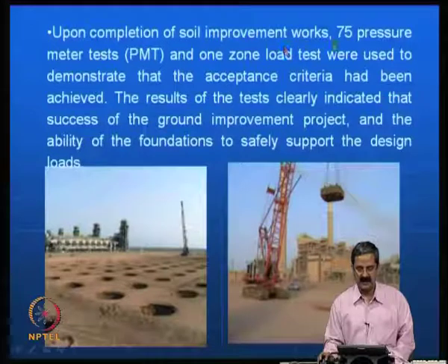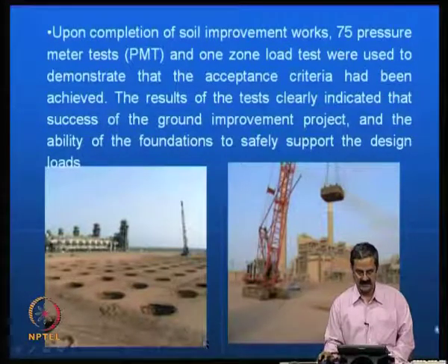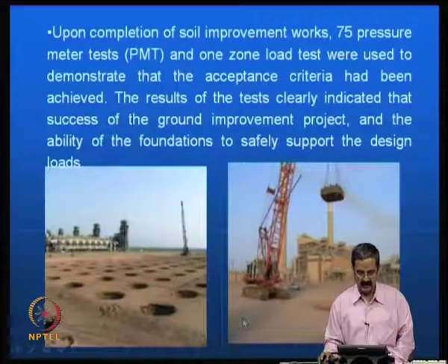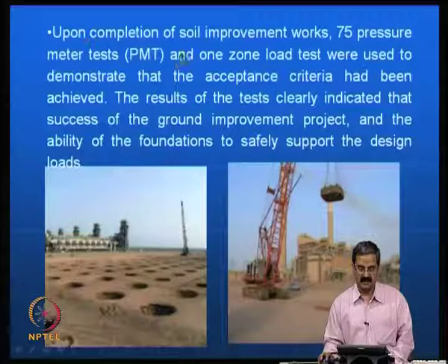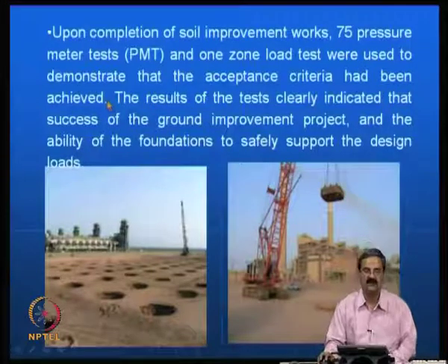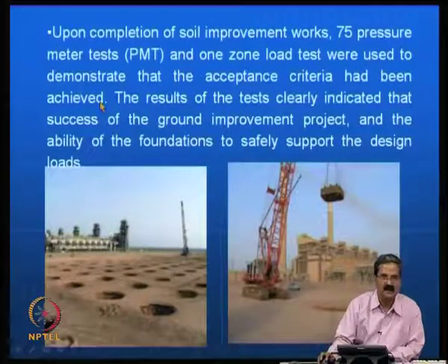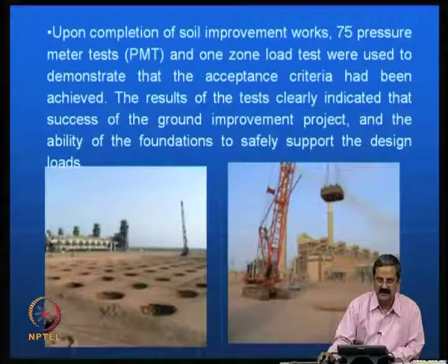Upon completion of the soil improvement work, this is the type of work that they have undertaken. This is from the particular company. They did 75 pressure meter tests and load tests to demonstrate that the acceptance criteria had been achieved. The acceptance criteria are what? The bearing pressure and settlement.